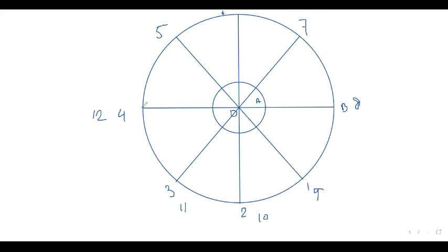After A, it will come here. This B position will be here. When A goes from A to point B, the position of the point A will go in this direction as well as rotate in this direction. So the last position will be at this point. Now we know OA equals 30, OB equals 90, so AB equals 60 millimeter. Now it is given 1.5 convolution, so we divide the circle into 8 equal parts. So we divide the AB, 8 into 1.5, so this will be the 12.